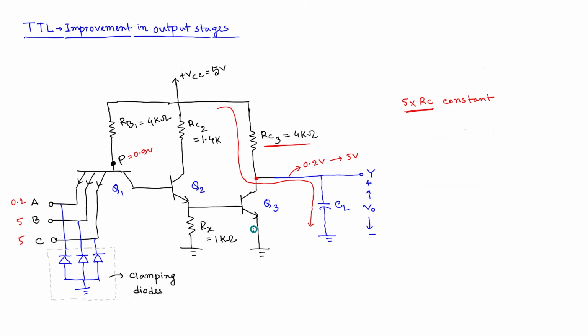So what you have to understand, in this portion of the circuit, the two things we have, the transistor at the bottom and resistance at the top, they have specific purposes here. The transistor, whenever turned on or in saturation, tries to pull the output down to 0.2 volt.